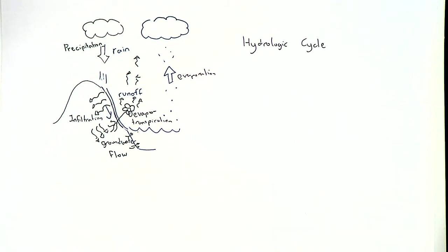And sometimes we don't want that. So sometimes we can have an overabundance of water. Water resources would consist of controlling that runoff. We can control it through a storm sewer system. We can control it through a detention pond. Or we can control it through pre-construction methods, such as not adding that much asphalt. Right? So there's different ways that we can control these water resources. But stormwater is not really the only water resource that we have.